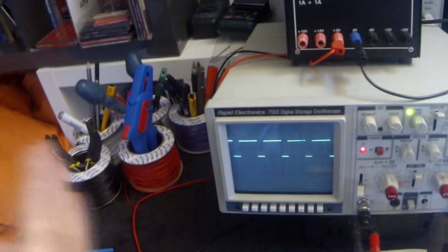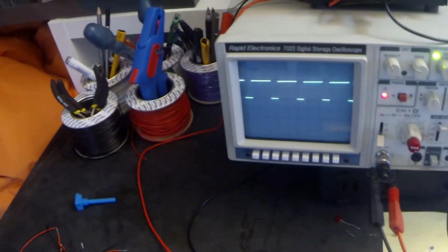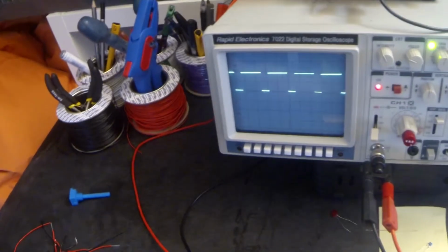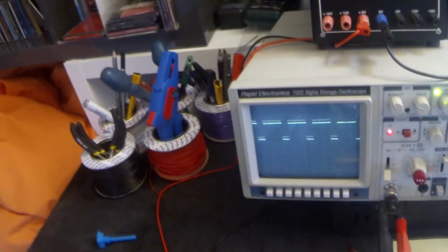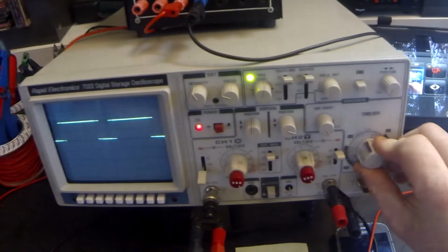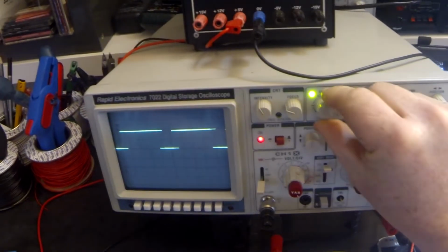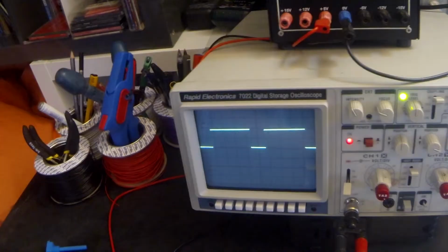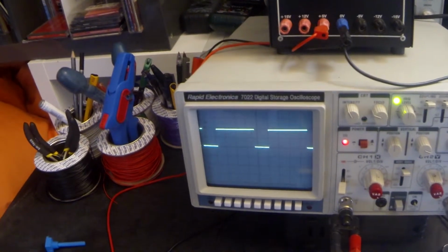And there we go. Now you can see on my oscilloscope trace, I've got a lot more divisions on the screen. Now that must mean that it's flashing a lot quicker. I've changed the value of the resistor for a smaller one, and now I've got far more divisions. It's more compressed. So what I'm going to do, I'm going to change my time base. There's a little trigger button there as well, which will just settle things. So there is my trace. I'm going to change it so I'm starting on a vertical line.